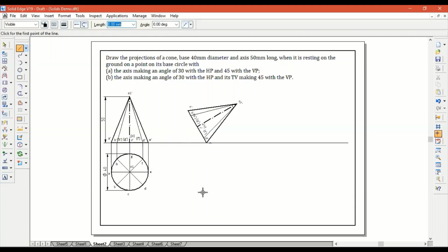So in order to draw the top view in the second stage, you need to identify whether the apex or the base is closer to the observer, who's going to be up here. Obviously, for the observer, the apex is going to be closer, meaning that the base is not going to be the one that is visible. Nonetheless, we're going to mark all the points of the base. So you have A, A1, you have B and H in the same line, but B2 have to mark them, remember, same vertical, whereas B and D are on the same horizontal. So there's D,